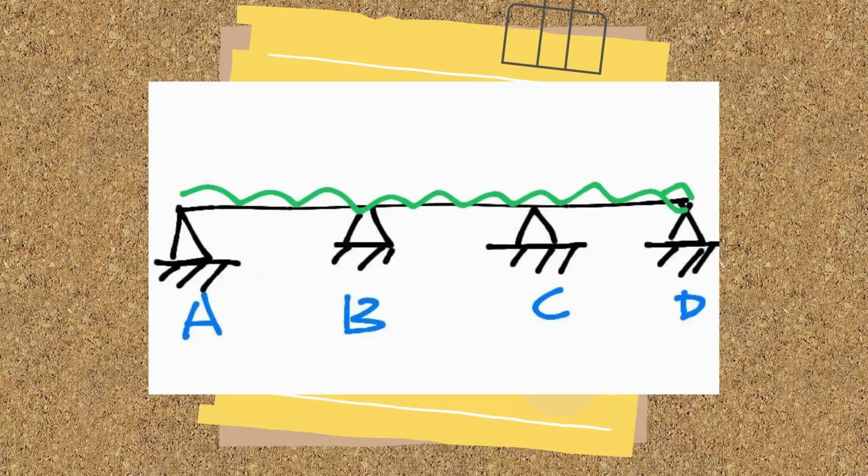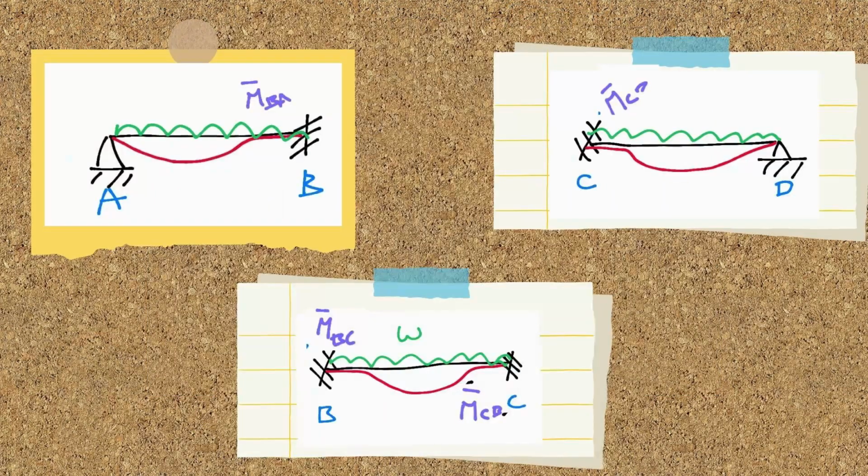There may be a case in which we have a hyperstatic beam which has more than 2 simple supports. In this case, the middle supports are changed and embedded to make use of the method. So the first section is articulated, embedded. The second, embedded and embedded. The third is embedded, articulated. And with the same methodology it is solved: we separate the original beam into 3 simple beams, and now we solve beam by beam, making it simpler.